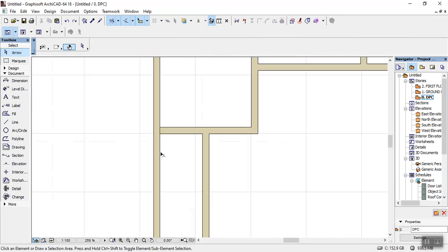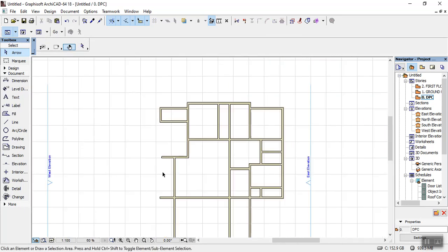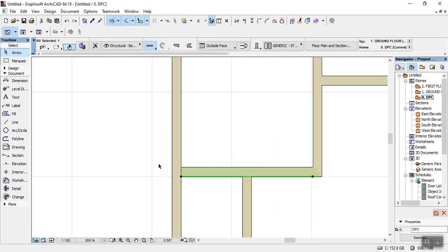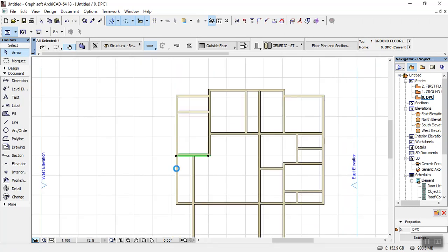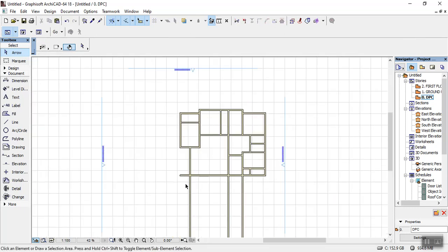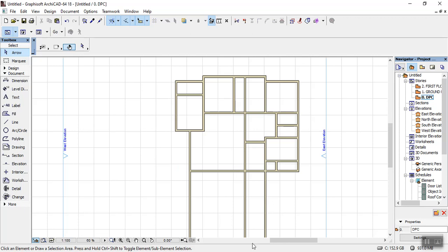Okay, if you observe very well, by the time I delete, it's going wide because this particular wall is not touching it, it's not connected. So make sure when you're placing your walls, they are all connected. So I'll take this off because I don't need it anymore.